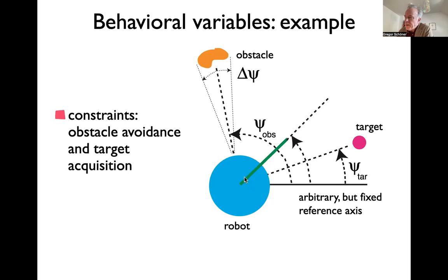And the maybe more intuitive thing that many of you might think of initially is that we might want to determine the heading relative to the robot coordinate system. Like this is where the robot is looking forward, right? And this angle here would be the bearing from the robot's point of view of this target, which is called in German Peilung, how we would be looking at this target. Now that is actually not a good variable, because now if you rotate on the spot, that value changes.